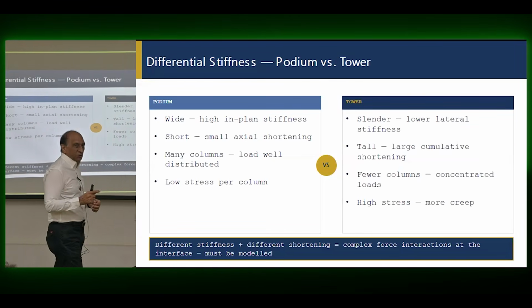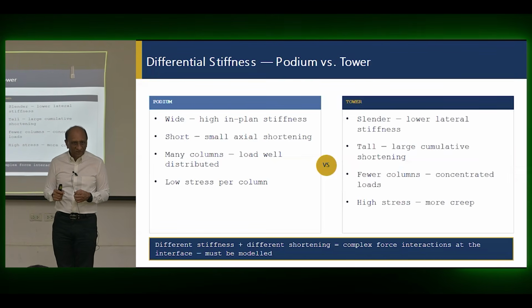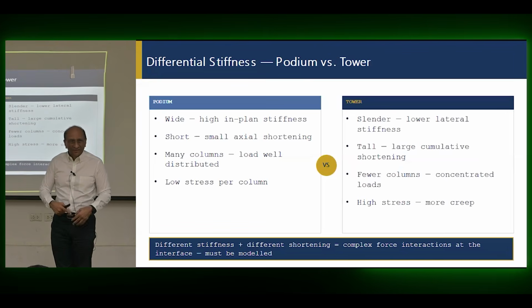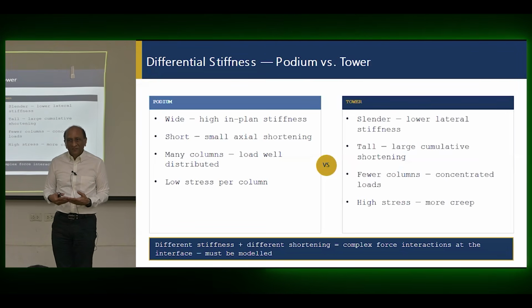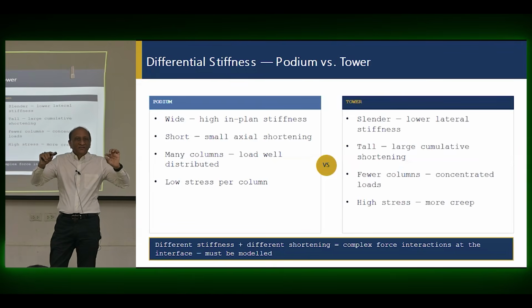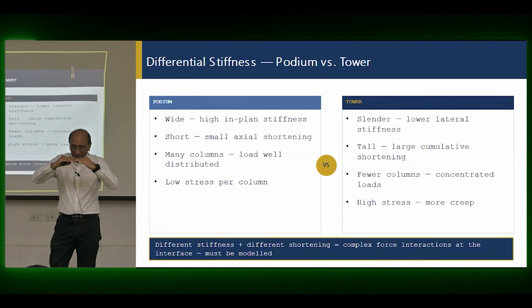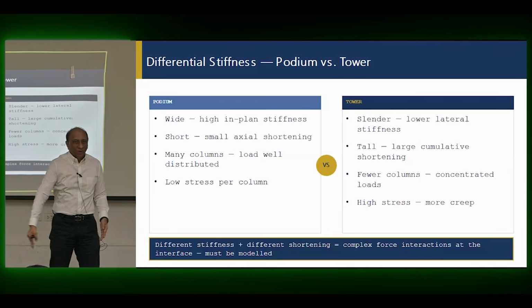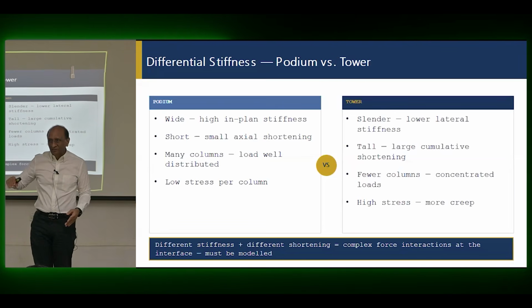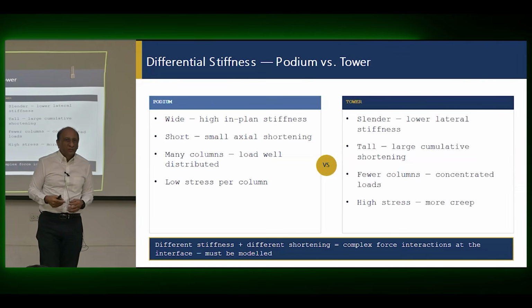Because people don't like expansion joints. Remember, these days expansion joints are a no-no in construction because they leak, they create problems, they're a maintenance hazard, they break the floor. So most of the people and clients do not want construction joints in the buildings anymore. So what you need is a kind of leveling slab in between, which can move up and down. So rather than an expansion joint, you just extend it to maybe a 4-meter-long soft slab around that, which can accommodate the movement without cracking. And still the building is connected.